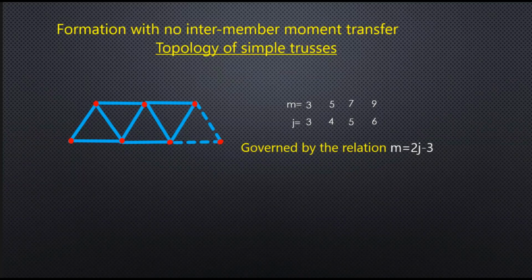Right. It can also be written like this. The indeterminacy is members plus number of reactions minus 2j. Right. Both ways I can always solve a system. What is the big thing about it? Whenever I see,